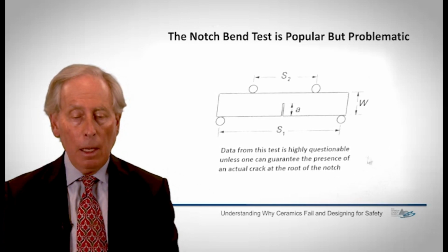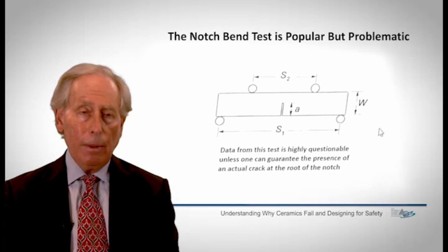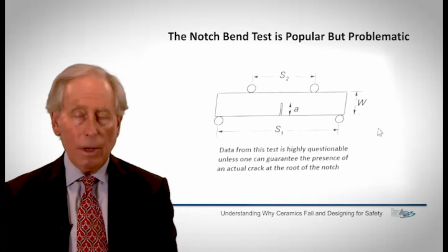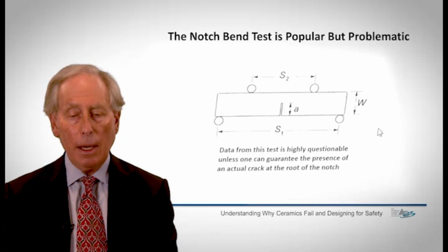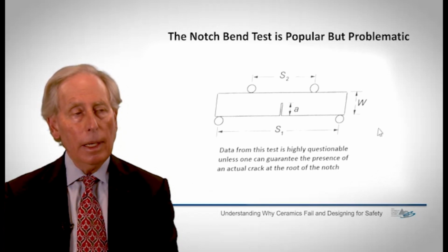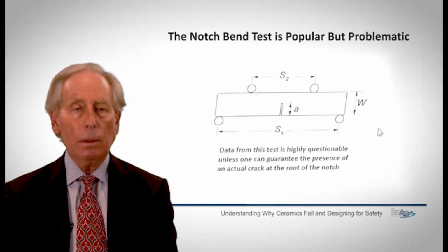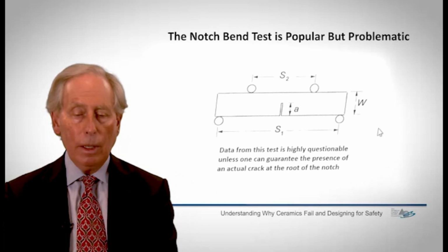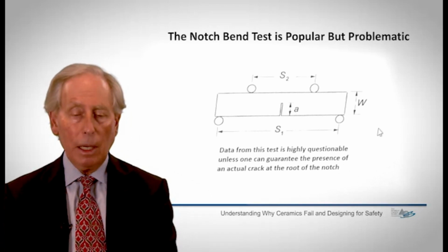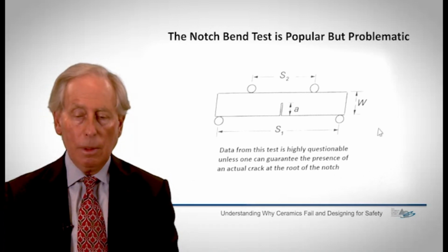But data from this test has been shown to be highly questionable. The reason being is that a sharp crack isn't always formed at the tip of that notch, or if it's formed, it's not formed throughout the entire thickness of the material. And the data from this test is variable. It typically overestimates the real resistance to fracture. It overestimates the fracture toughness of the material. And I would avoid using this if at all possible. It's a simple test, but because of these issues about the accuracy of the data, it's probably not a very good test to consider.